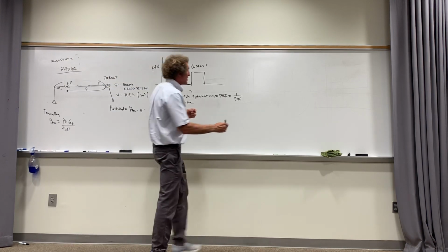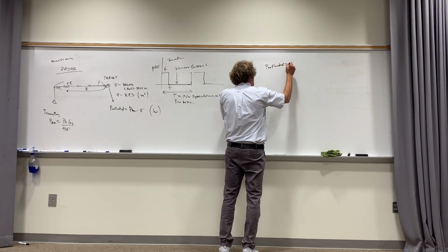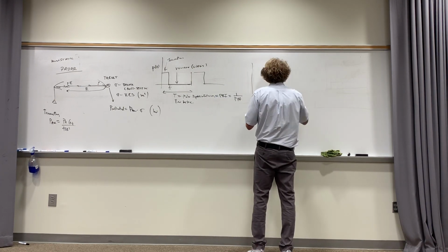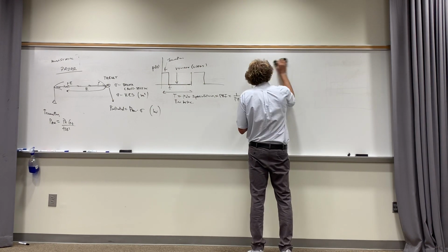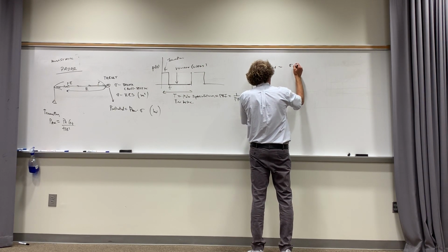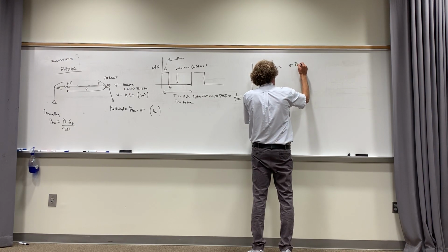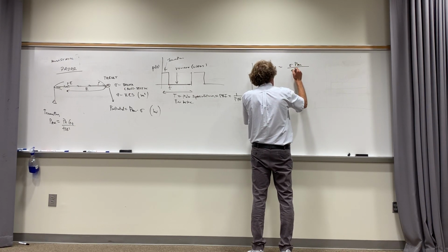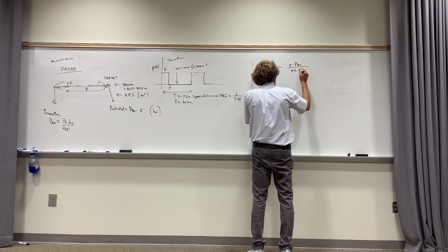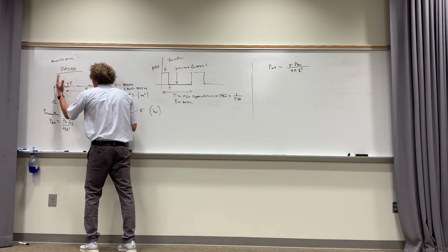So now I come over here and I say P reflected, I should say power reflected density, I'll just call it P reflected, small ref. Here is going to be sigma times P, the average power, and then it's over 4 pi r squared. Why r squared? Because it's reflected, and now it's going to come back and hit this.